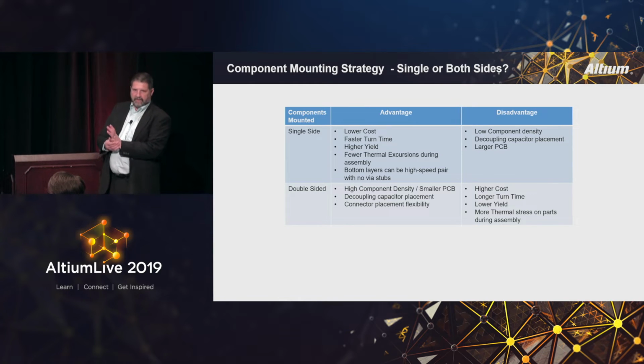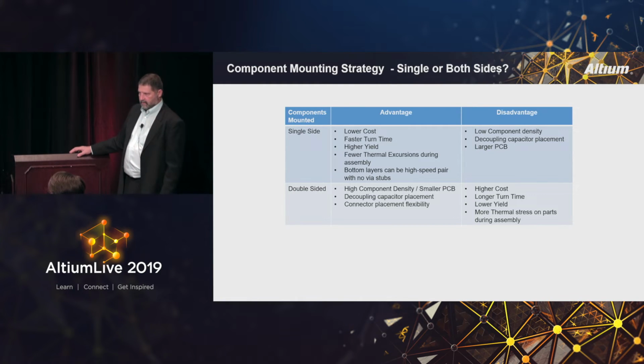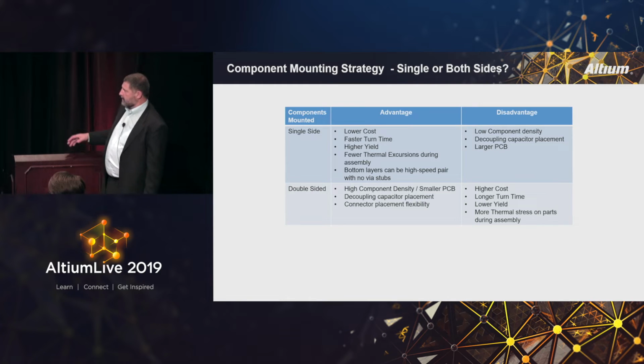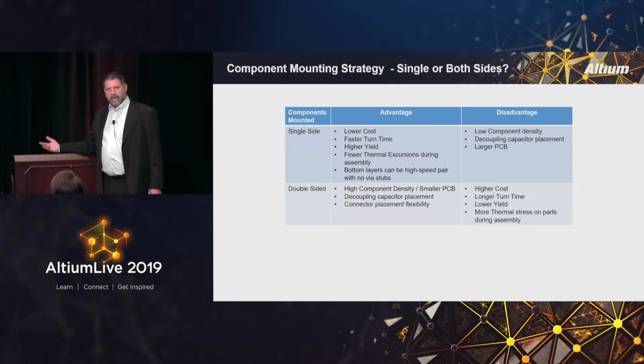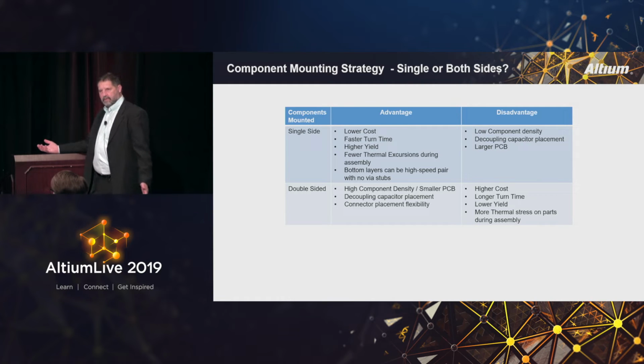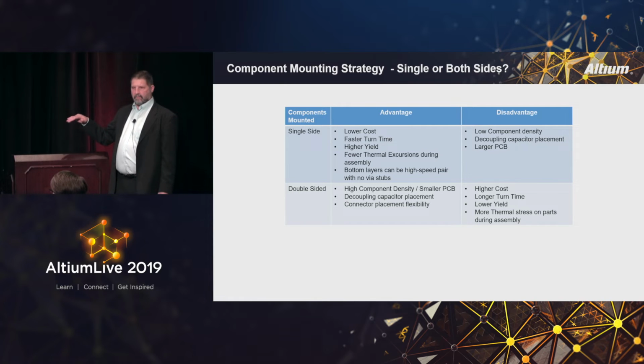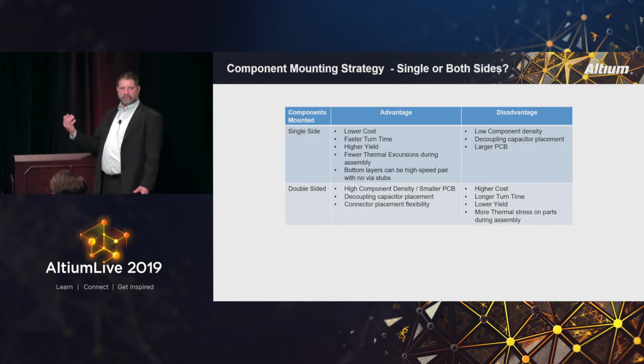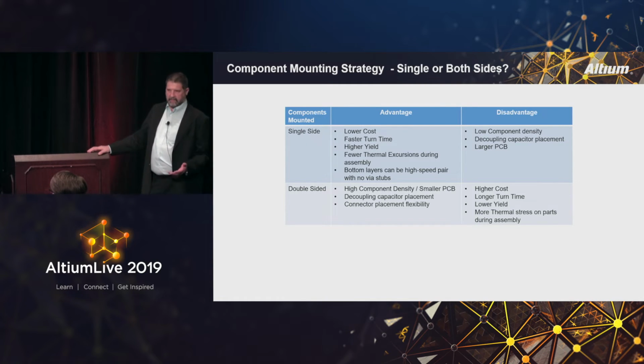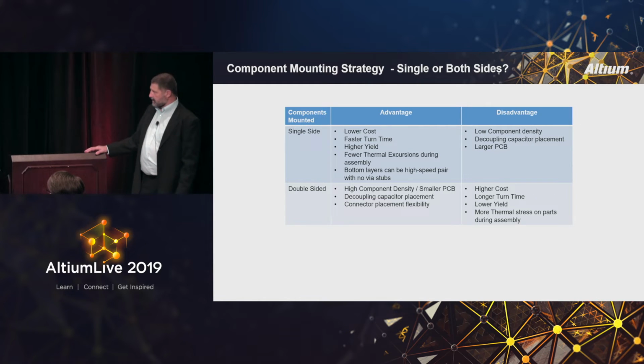But again, if you have through-hole connectors on both sides, now you're going to have 4 operations in this for thermal, because it's typically a different process for through-hole parts than it is for surface mount parts. And then we typically have to allow room for a fixture on the bottom of the board, maybe 5 millimeters or 3 millimeters with a custom fixture. So we have to be aware that on the top we can put parts right next to a connector, but on the bottom, those through-hole pins typically have to have like a 5 millimeter clearance, or if we pay more for the fixture, they can machine tool it and get a 3 millimeter clearance.